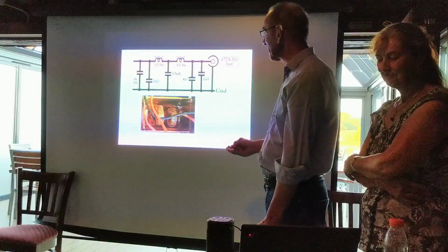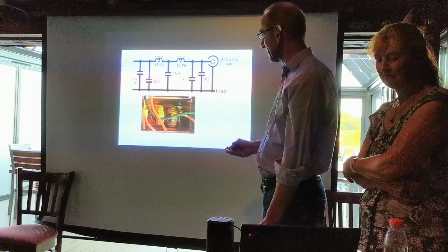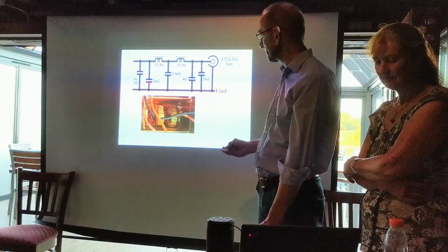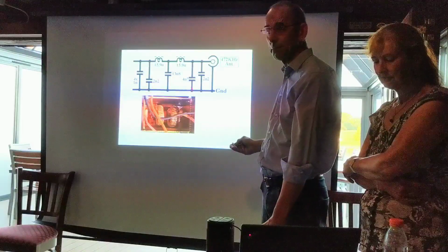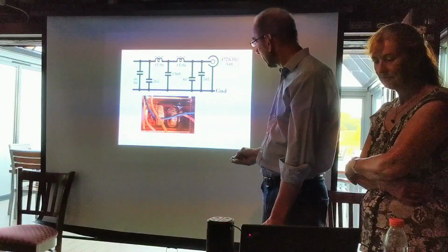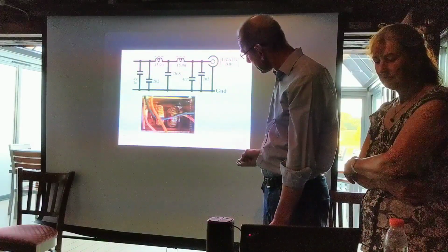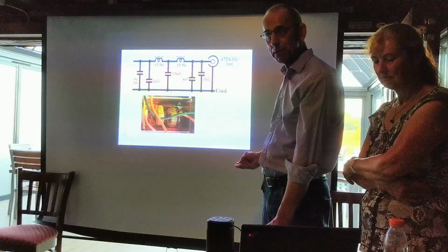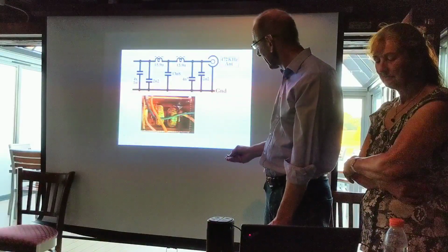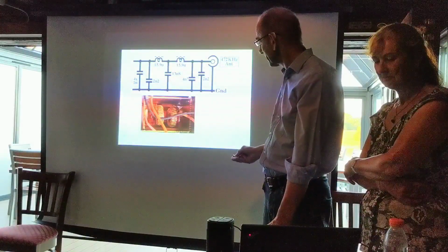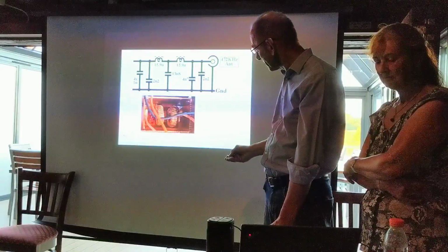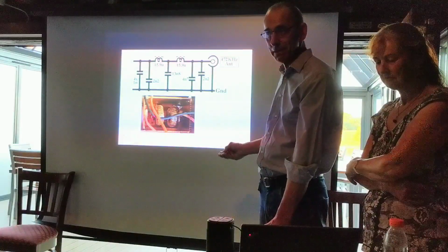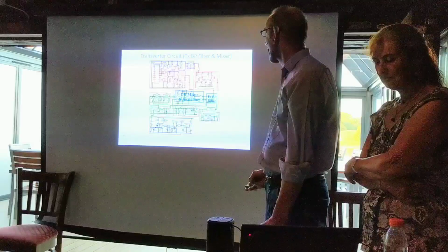I noticed it wasn't attenuating the third harmonic as much as it should, so I just increased the capacitor values a bit and played around with it until it did. And here it is. Two toroids, I think they probably came out of some switch mode power supply from a PC or something, wound up and measured on my inductance meter, and some capacitors jammed down the back here, a load of stuff all put together to get the right values.